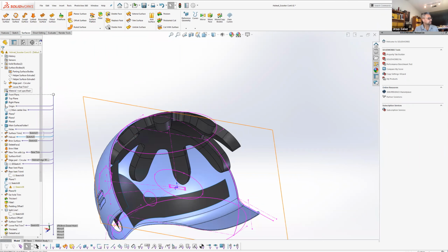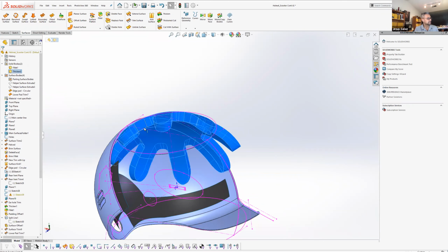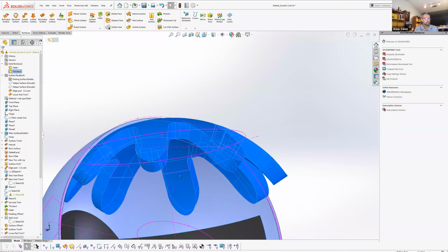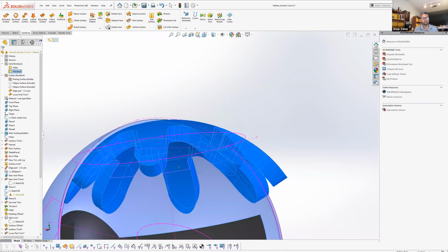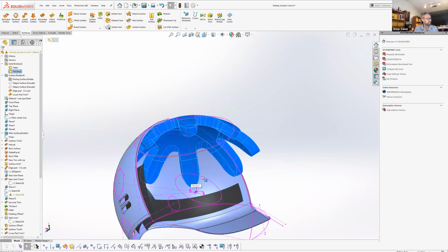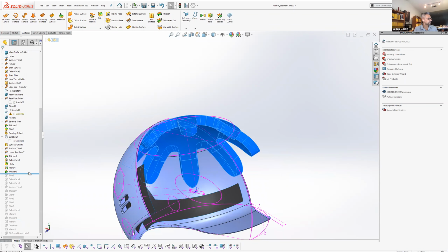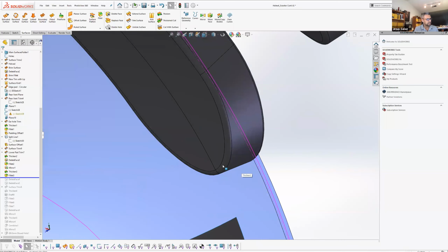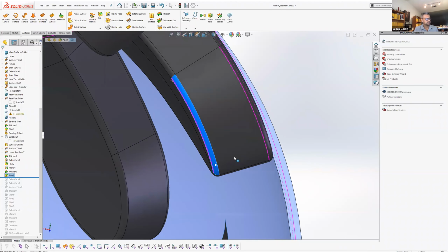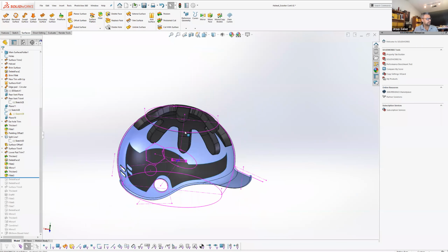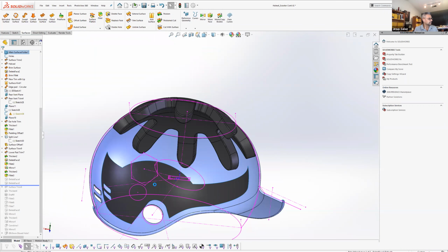So now if I look at my folder, you can see that there's this solid element. And then you can do other things like shell or whatever you may want to do. Maybe 3D print this possibly. But now that it's a solid, you can do that. I added some fillets to the overall edges, basically all of these edges here, inside and outside, for that padding. And I'll upload this model as well.